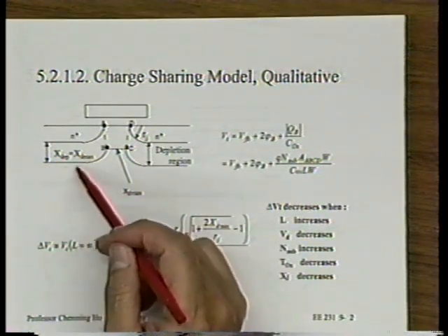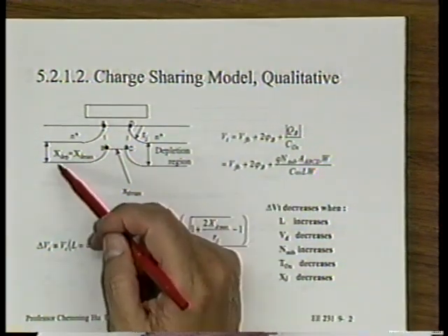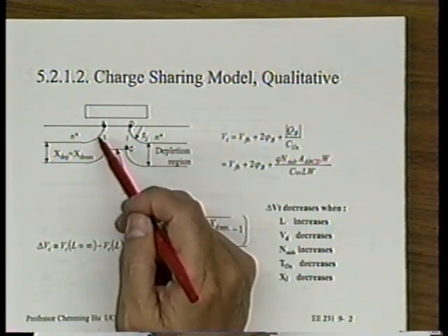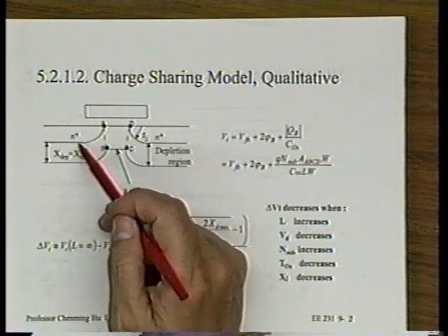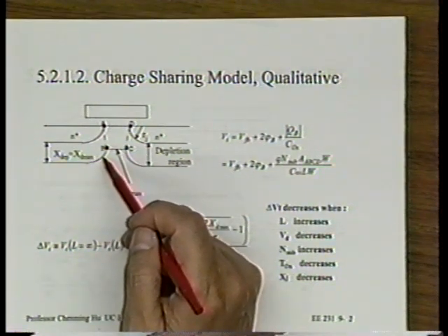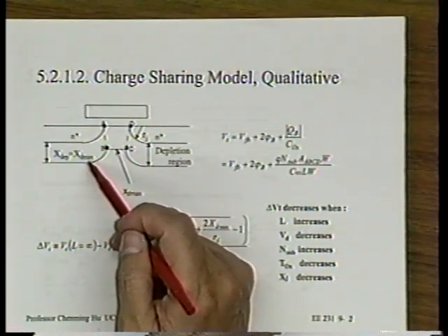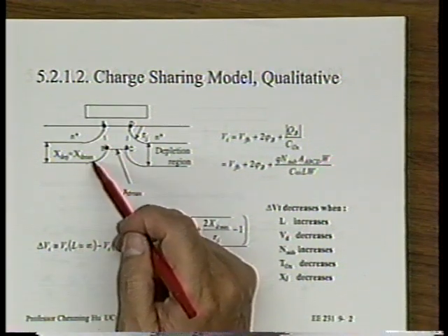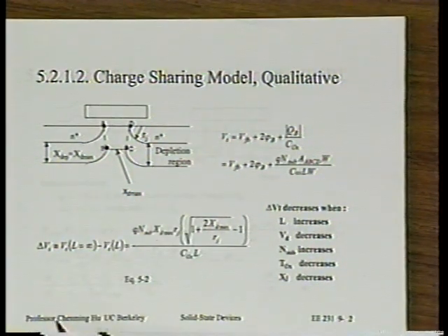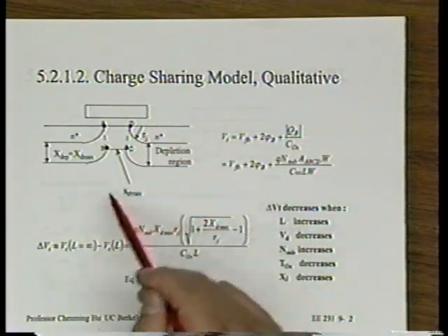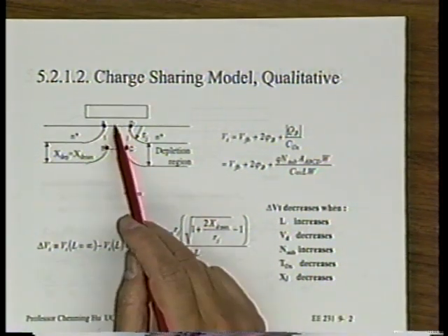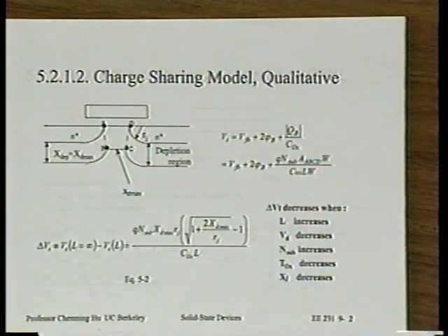Just draw a curve like that. You can probably visualize it. We pick the depletion region width here, and then draw this portion assuming a cylindrical shape of the junction, and therefore draw another quarter circle with a larger radius. The radius is equal to the junction depth plus X depletion. Is that right? Yeah? Do the same thing on the drain side. And in the channel, we draw a horizontal line at the depth of XD max below the surface. Okay? You see how that's established?